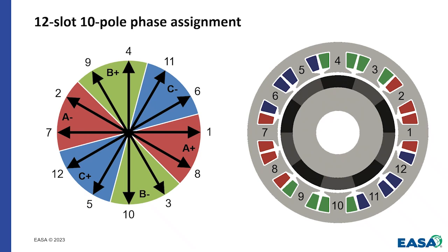So this group, these 2 coils over here, we're going to connect those with opposite polarity to what we connect these 2. And when we do that, we'll find that the 4 of them work together close to what we would want for that A phase voltage.